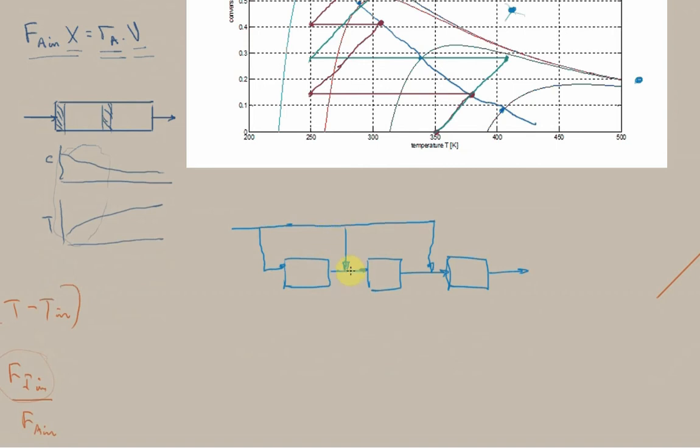But then we are going to get this stream coming through, which is the same as the temperature over here. So this lower temperature mixes with this higher temperature, so the temperature will drop. Also, the concentration of the reactant will go up because we are adding this fresh stream of reactant in at this intermediate point, and the same applies here. So we get the lower temperature going in here and a higher concentration of A. So we restore the reaction rate and we restore the temperature.